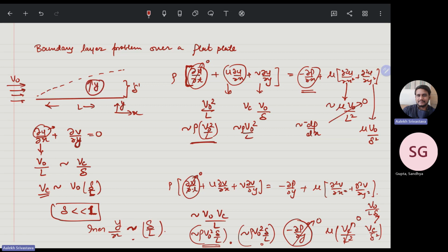So what is the merit or the good point of this? Suppose that up to the boundary layer, viscosity is felt. After that, no viscosity is felt. So whatever the pressure condition at this point can be directly imposed on this plate, because the pressure is not varying with y.